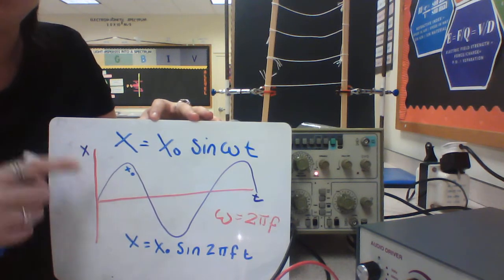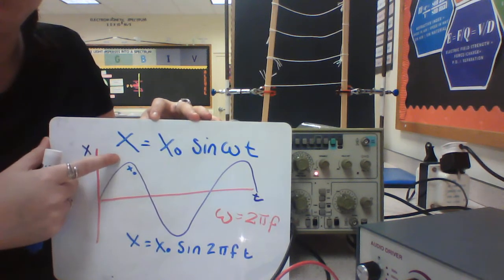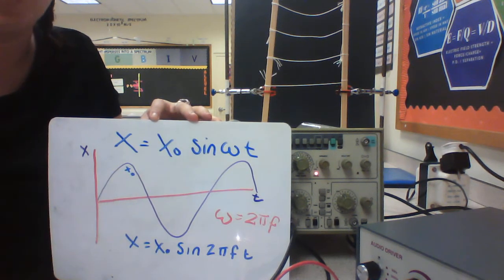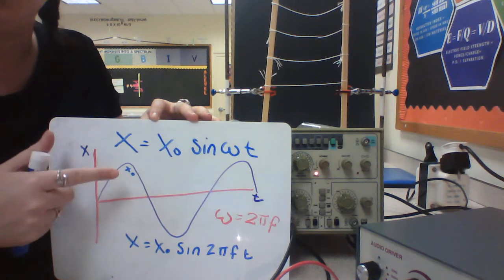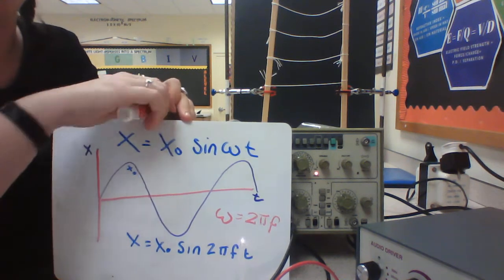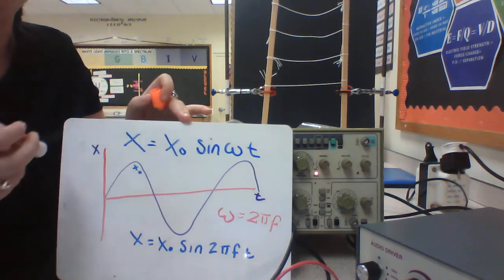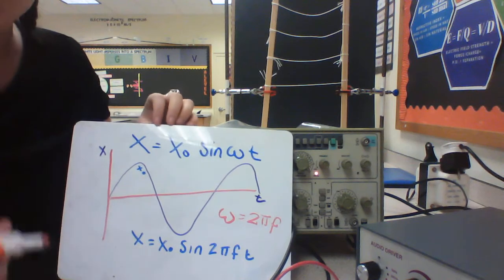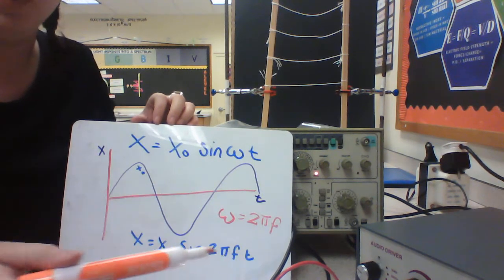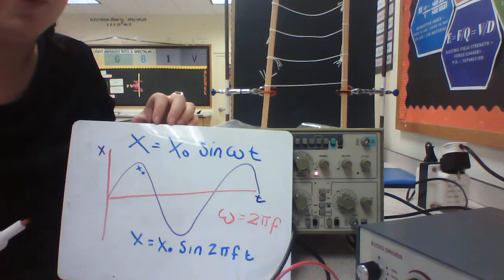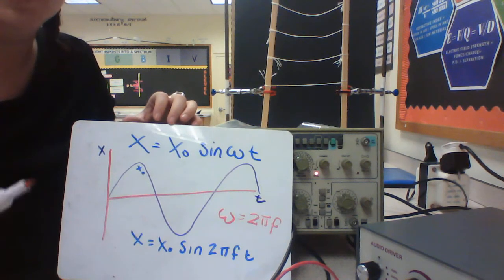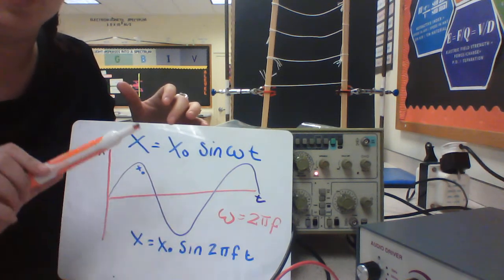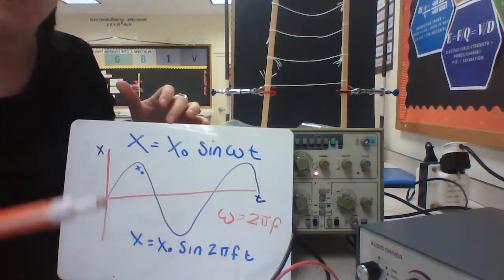There's two different voltages that we care about. So there's this peak voltage. This isn't what we talk about when we say, for example, that the Cayman Islands power supply is 110 volts. That isn't your peak. That's something known as your RMS current, or your RMS voltage, because I'm talking about voltage. Your RMS, root mean squared current, is, it doesn't matter which way the electrons are moving through this resistor. They're moving that way, they're moving that way, they're moving through resistance, so I get power loss. I get the bulb heating up, I'm losing energy. It doesn't matter if they're oscillating to the left or to the right, I'm getting some power loss.